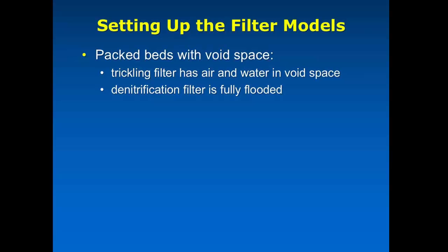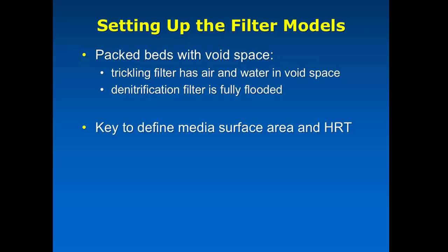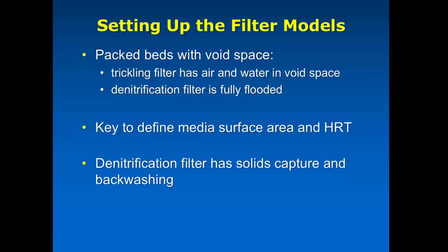And then the denitrification filter is different, though. Generally bottom loaded, sometimes we have both bottom loaded and top loaded, but bottom loaded, and it's a fully flooded filter, so there is only water. There is no void space of air in the denitrification filter. So the key to setting these ones up is to define the media surface area correctly and also the HRT of these particular systems.